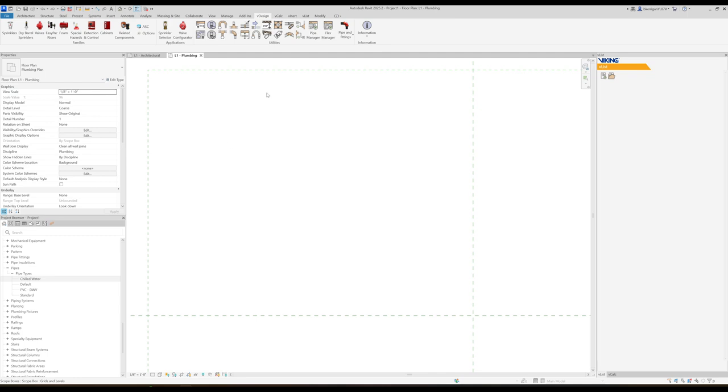This video will introduce the Pipe Manager utility available in vDesign and Revit. It is available on the ribbon via this Pipe Manager button. This is a new utility that replaces the legacy pipe and fittings option for generating pipe types with routing preferences all set up for you.